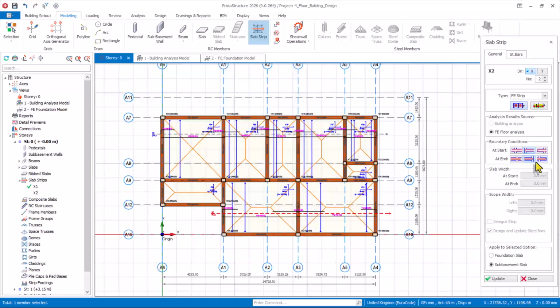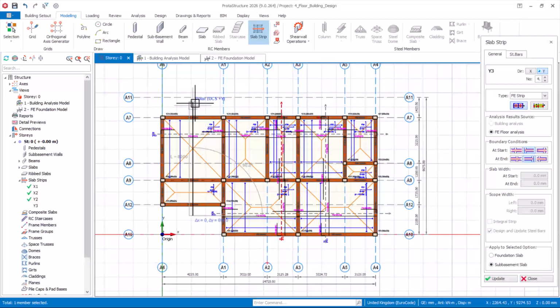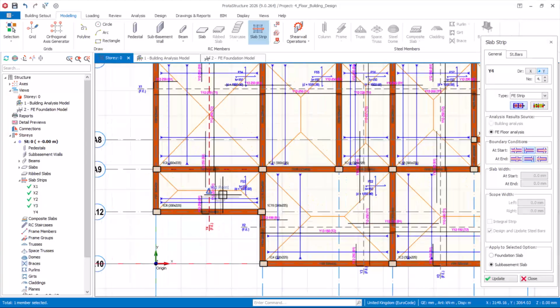Okay. So now what you just have to do, change the directions from here, and then we'll go to the Y direction, pick the first point, hold the control key, and then place the slab. Let's see to design in the y directions if it will pass. Okay, it has passed in the y direction. It's only in the x direction that is giving us that insufficient slab thickness.